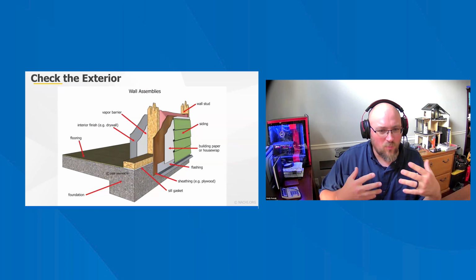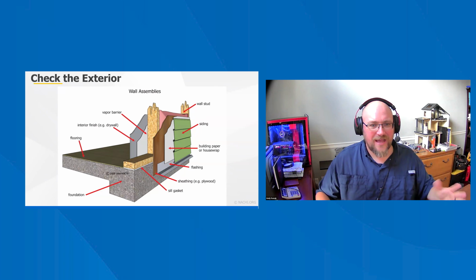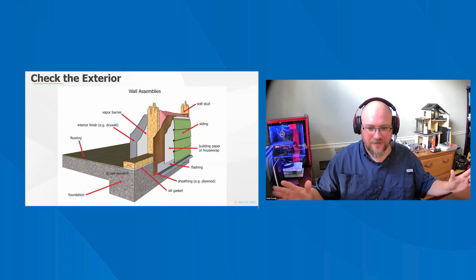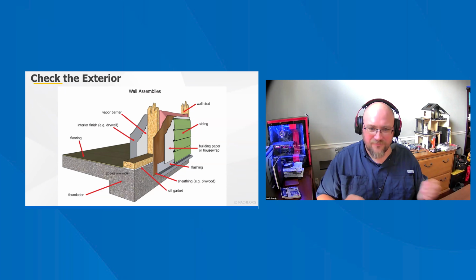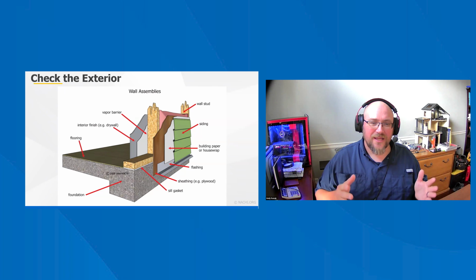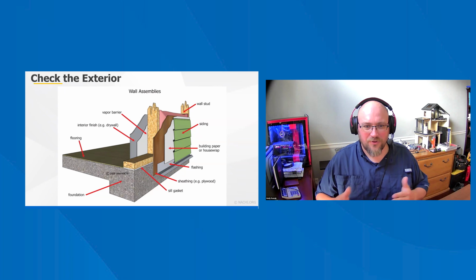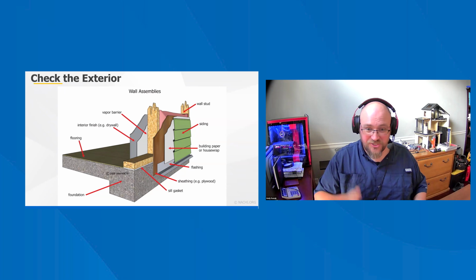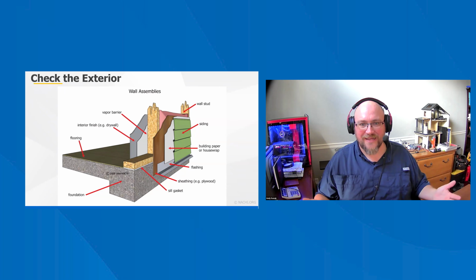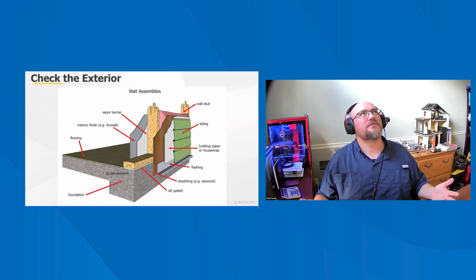House wrap is, I think, more forgiving because you have a huge sheet of WRB, and that is shedding water away. Even if you have penetrations that are not air sealed, you're less likely to have a problem than if you use zip tape flashing, where there's a joint every 4 by 8 foot or 6 foot.